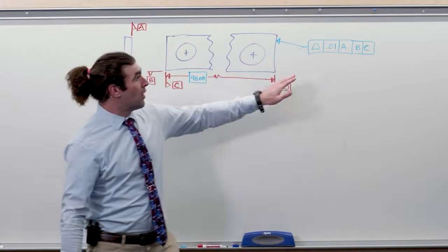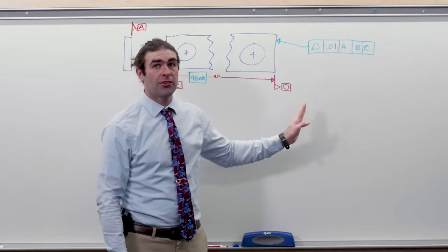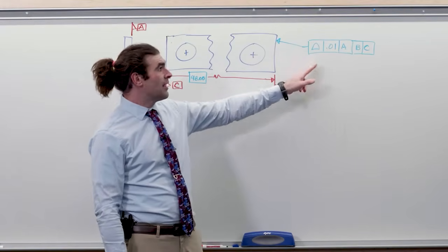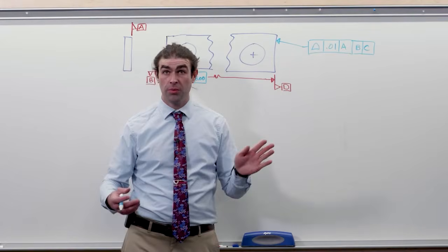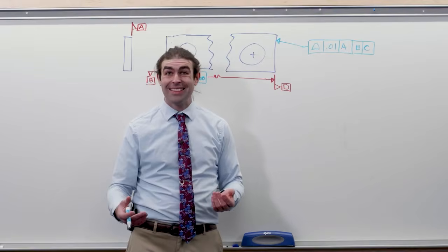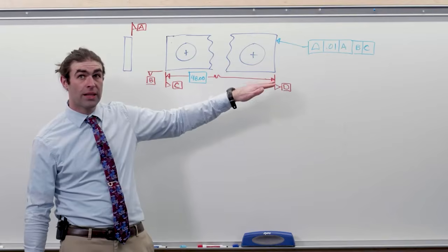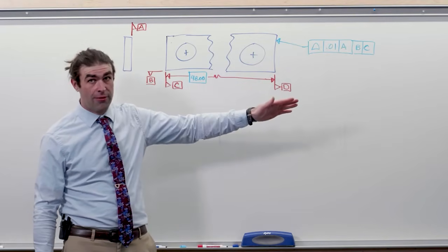Okay, our first option, profile to A, B, C, that will establish D just fine. But measuring a profile of 10 thousandths from 48 inches away could be difficult, right? We might want to open up that tolerance to make it easier to inspect. This is the most restrictive we can be, a single profile to our datum reference frame.